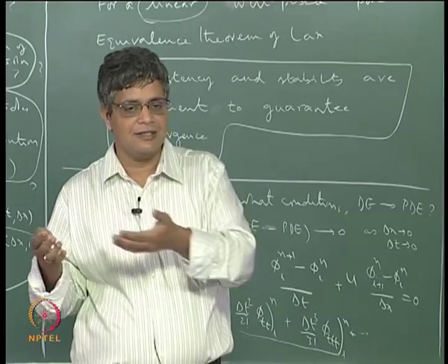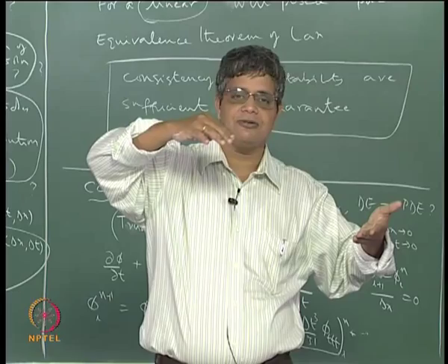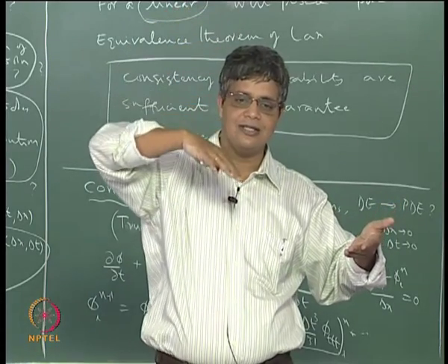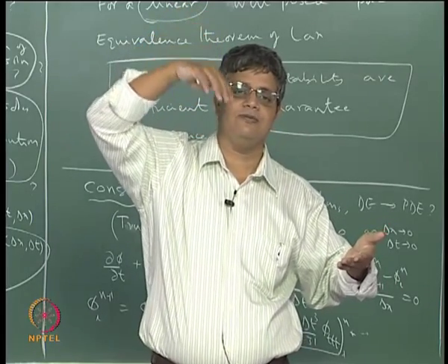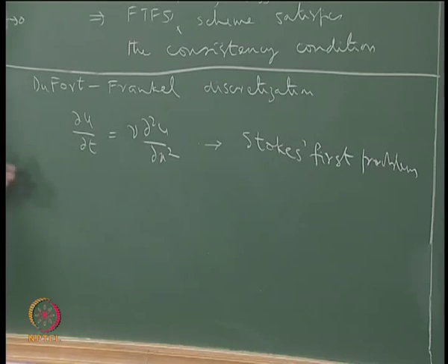So we will find that because of the plate movement in this direction, the fluid which is above it also starts moving, above it also starts moving, and above it also starts moving. So the variation of the development of the velocity profile with respect to time is encapsulated in this equation, is given by this equation, and this is known as Stokes first problem. So this is not any artificial problem, this is quite a fluid mechanics problem.